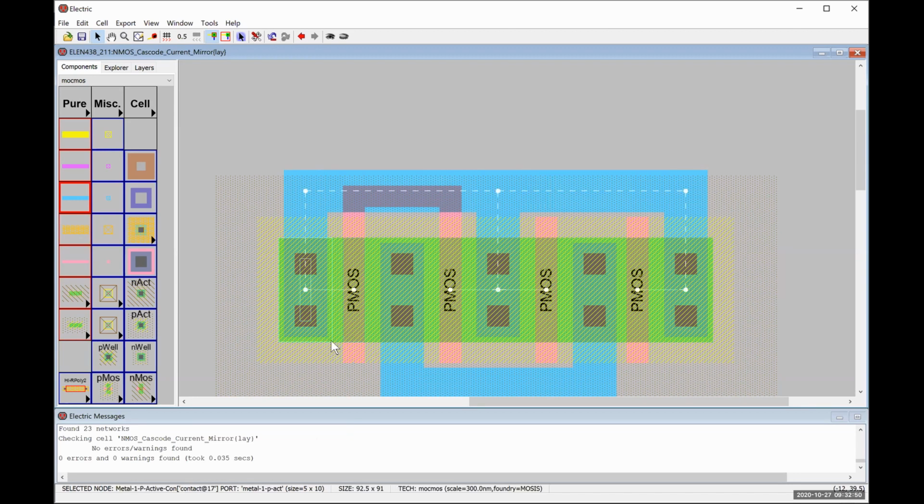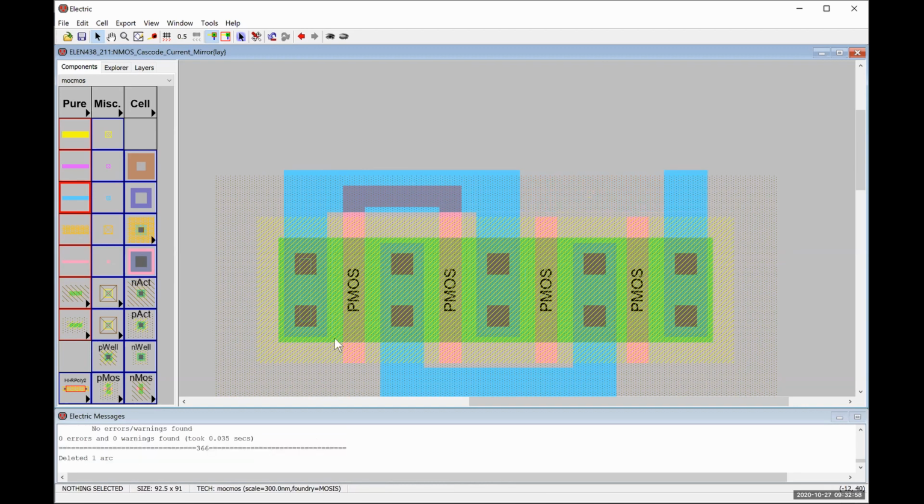So what I'm saying is that when we only had up to the third transistor, if this guy over here weren't connected, this distance from here to here is 10. And then we have another distance from here to here, making 20 for our source or drain. If we don't have this other transistor also to give us the extra 10, it's not a 30 by 2.